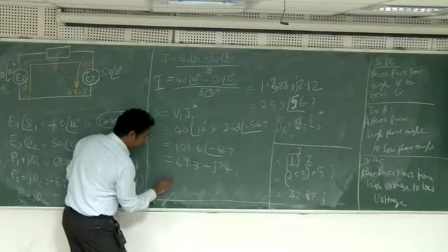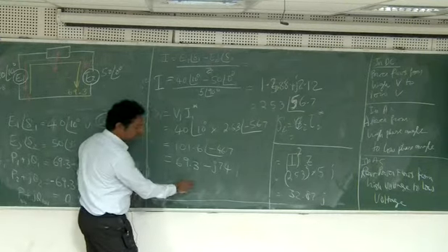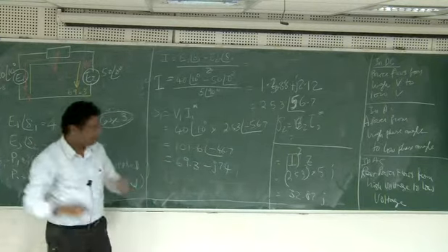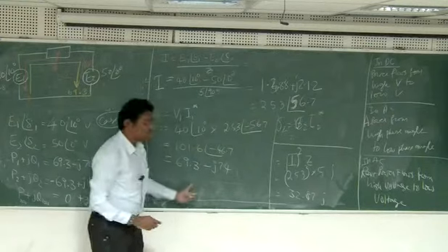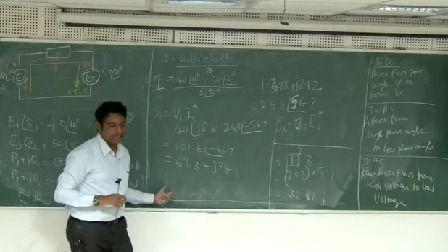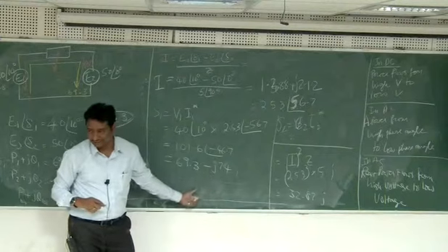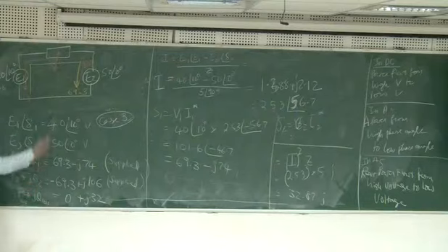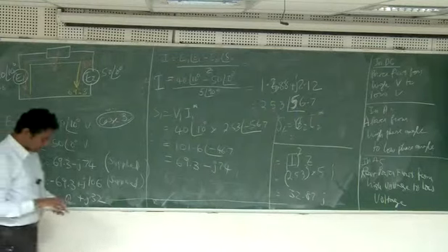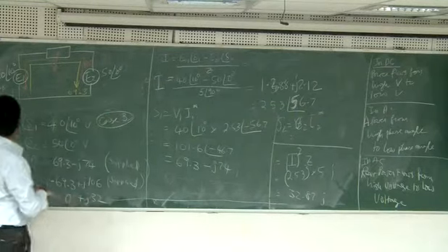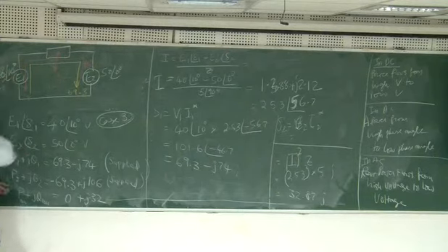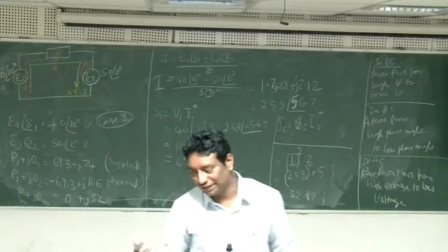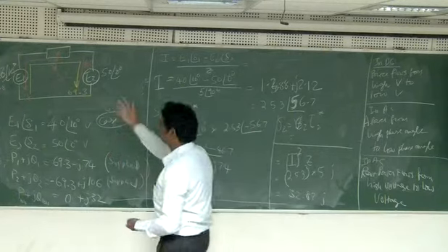So from source 1, the reactive power flow is coming like this. Source 2 also has reactive power flow coming like this. Both are supplying the reactive power and it is consumed here. However, the sharing is not equal. This may be slightly lesser and this may be slightly more, and then it is lost. So you can try that. You can write a small program, and in that you can make even magnitude variable, even delta variable. By varying E1 and delta 1, you can find out all this relation.